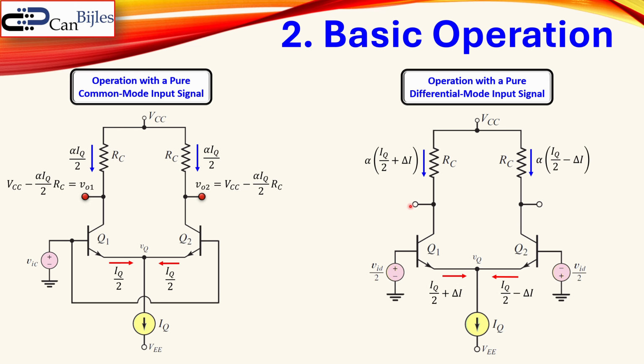Now what about the voltage VO1 and VO2? Well, that is again a similar analysis. So VO1 will be VCC minus the voltage drop across this resistor, which is RC times the current, which is just Ohm's law, and that is shown here. Similarly for the VO2, we get this expression again using Kirchhoff's voltage law, and we apply here Ohm's law to determine the voltage.